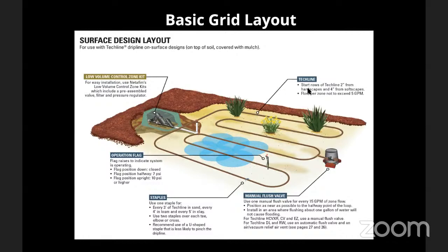And then just one quick note here, we'll talk about it later, but you always want your drip to be at least 2 inches, and I normally go up to 4 inches, away from the edge. So any path areas, concrete walkways, decomposed granite walkways, sidewalks, or anything like that, you always want it to be a few inches off.